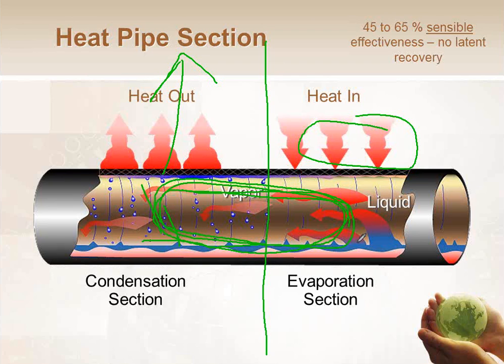It works great. It's a fantastic system, but just like with the runaround coil, it's only going to be able to do sensible energy. There is no latent performance because this refrigerant never gets down to the dew point of the airstream.